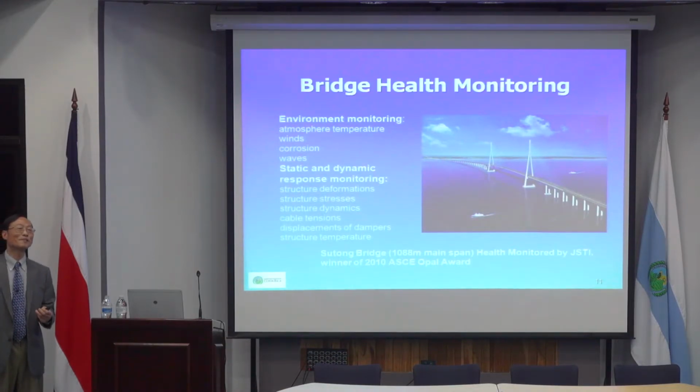So if the base frequency was 3.1 hertz, now it becomes like 2.9 hertz. You know something changed all of a sudden, and probably something is going on. You may do a really detailed inspection. That's why I think if you do want to do a measurement, the vibration frequency sensor is most important.